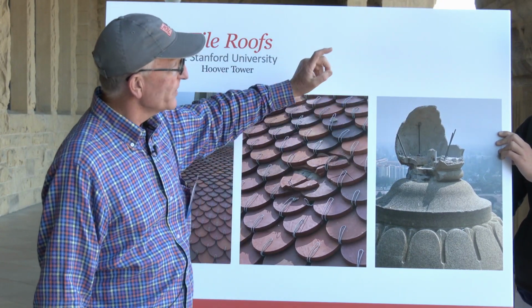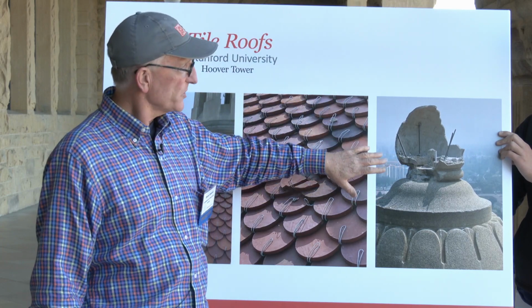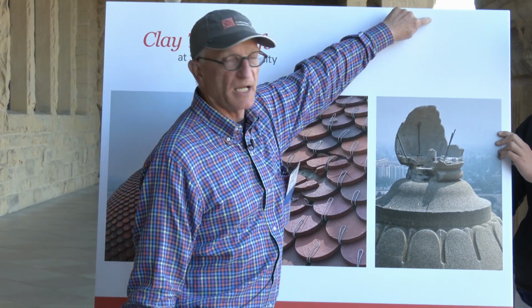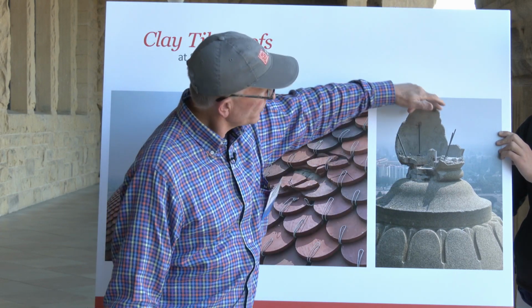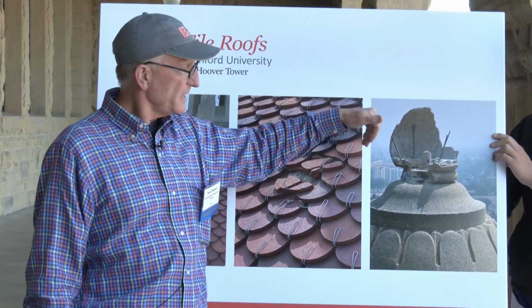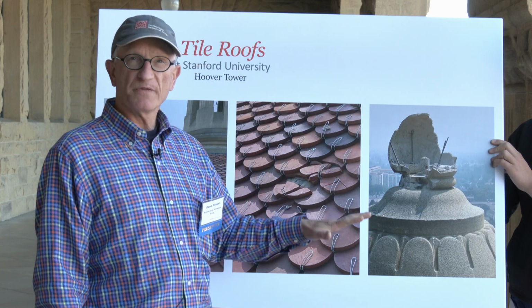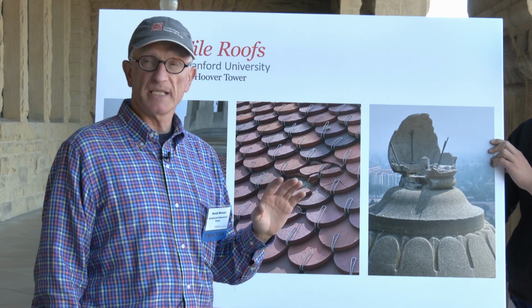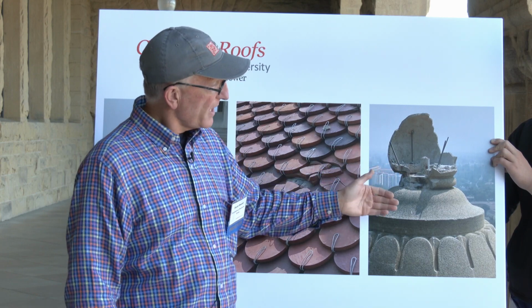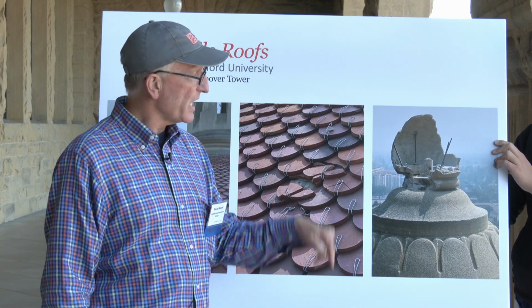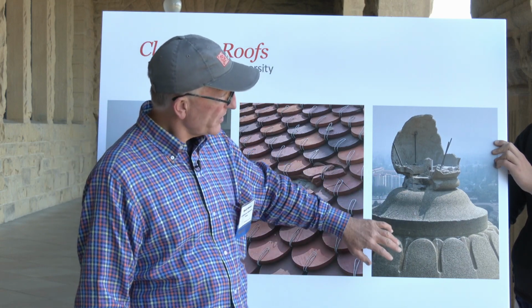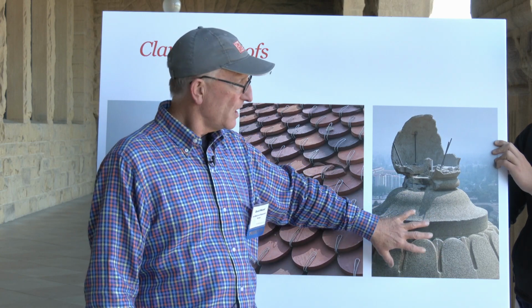As part of this project, we did put in a new lightning arrest system. It was a large rod, put 6 to 8 feet above, through this pipe into a new ball finial, and the cable was run down into the building. We had to do this very carefully. We had a special engineer who only designs lightning arrest systems, who came and made sure that there are no bends in the cable that went down all the way into the basement, where it went down several feet down through the foundation.